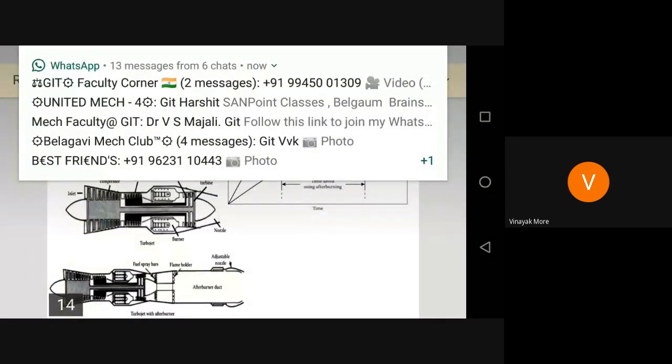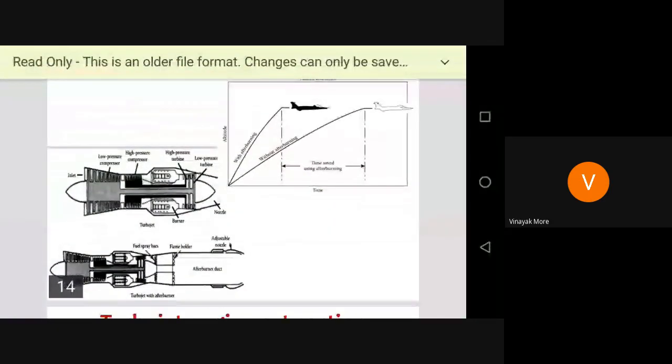So one shaft will rotate inside the other shaft, so that the first stage of the compressor will take the rotation of the last stage of the turbine, which is at very low speed. Then the first stage of the turbine, after the combustion at very high speed, is running the second stage of the compressor. So here we have two different spools, and later we can connect these spools with the requirement for power generation and other things, or else we can use it for aircraft engines.